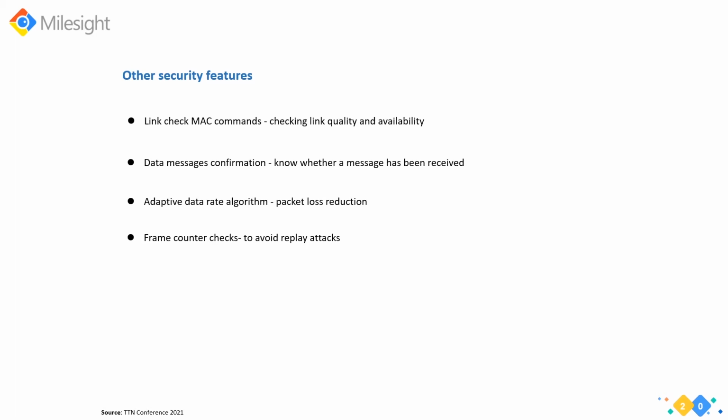And because we are working with a radio protocol, anyone will be able to capture and store the messages. Without the application session key, it's not possible to read the payload, because the payloads are already encrypted. And without the network session key, it's not possible to tamper with the payloads. But it is still possible to transmit the message again and again. It's called replay attacks.